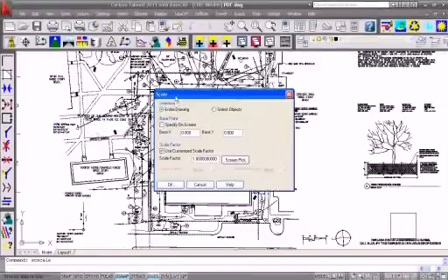And now we have a dialog that comes up that makes figuring out the scale factor on the drawing a lot easier. So what do you want to scale? The entire drawing or certain objects in the drawing? Just right in this PDF, so we want to scale everything. Use customize scale factor on this job. That's what we're going to do.